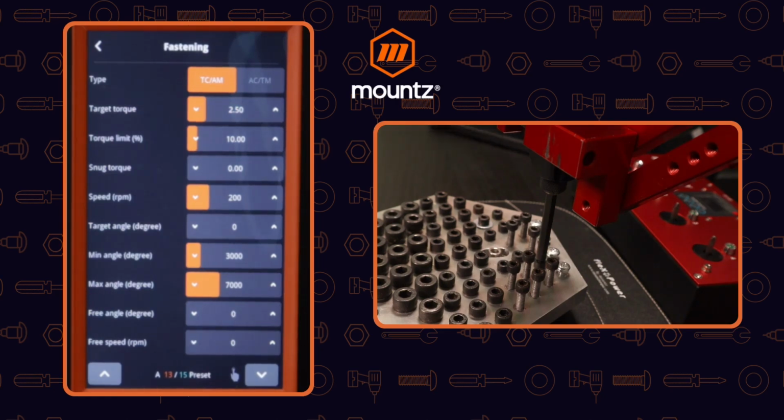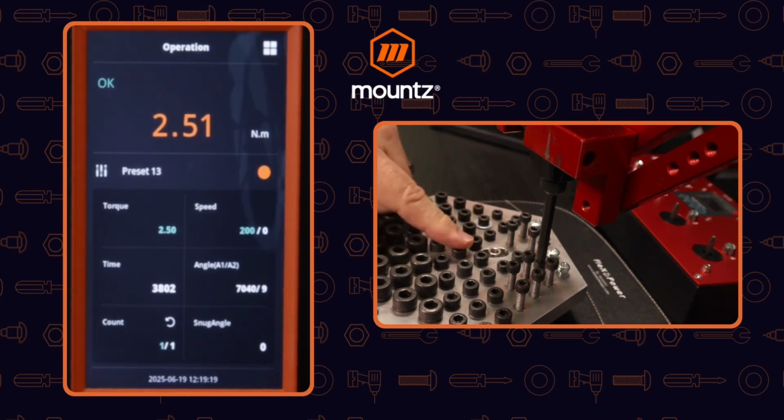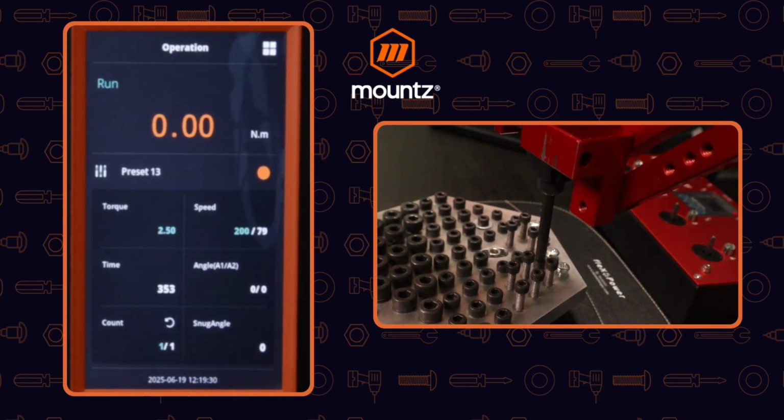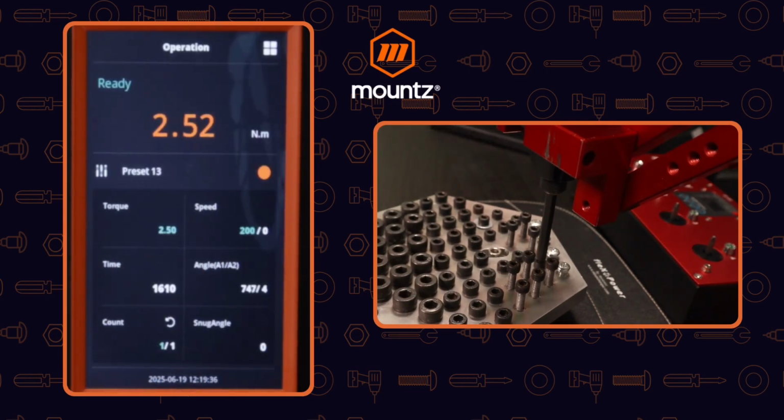Again, giving us the ability to error-proof the assembly for this particular fastener because cross-threading might be an issue. And so if we come back out, I'll go ahead and tighten a fastener that we've already tightened. By doing that, that will give us an error, minimum angle error. And so that then alerts the operator, oh, we have an error. That was the minimum amount, which would be associated with the cross-thread event.